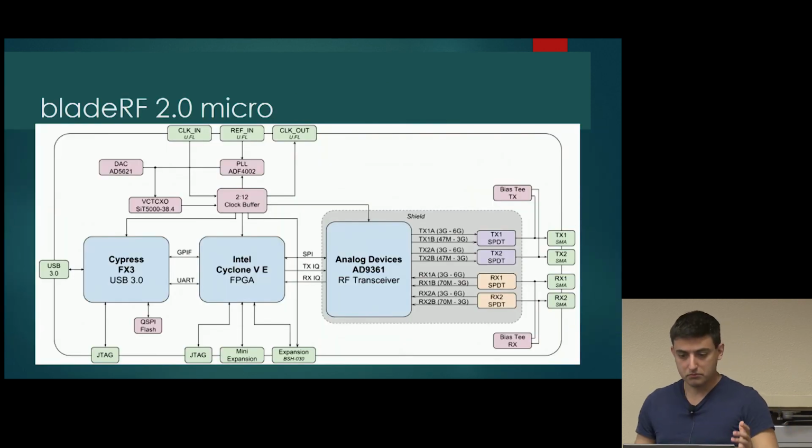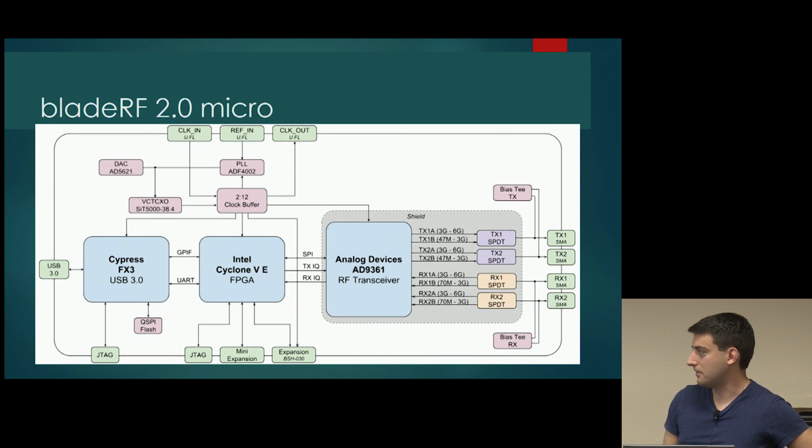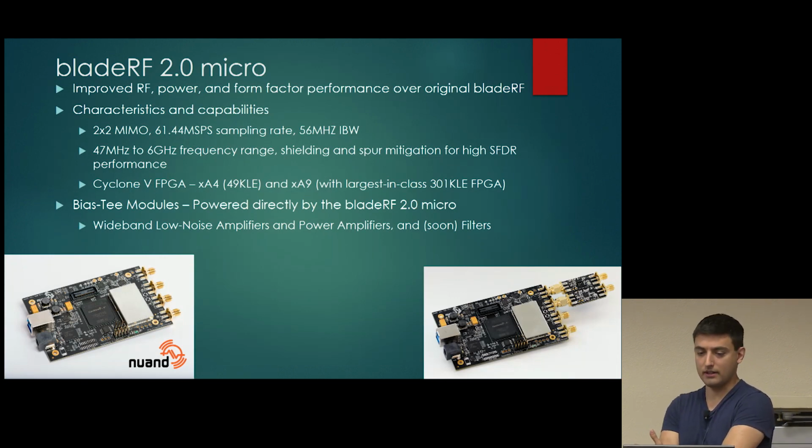I just wanted to take a couple of moments to make everyone aware of the bladeRF 2 micro. It's a revamped version of the bladeRF. It's a Cyclone 5 FPGA and AD9361 based SDR.